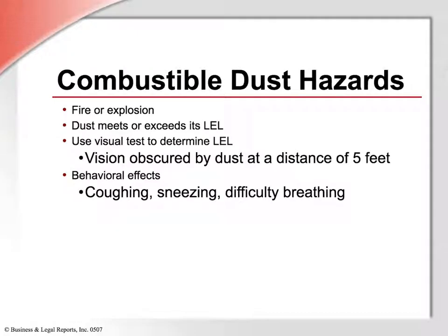Combustible dust concentrations are usually found during loading, unloading, and conveying of grain products, nitrate fertilizers, finely ground chemical products, and other combustibles. High charges of static electricity, which rapidly accumulate during periods of low humidity, below 50%, can cause some substances to spark and ignite a flammable atmosphere. These sparks may cause explosions. You have heard of times when grain bins or something like that will explode because of this type of atmosphere.